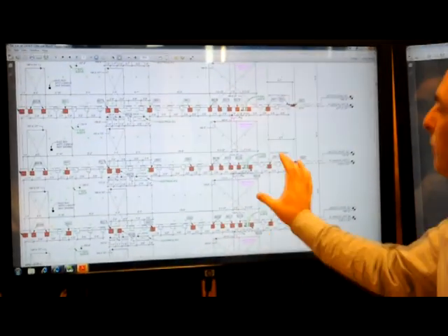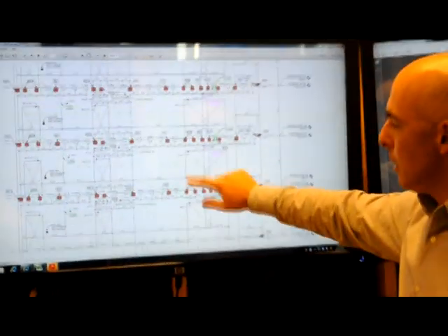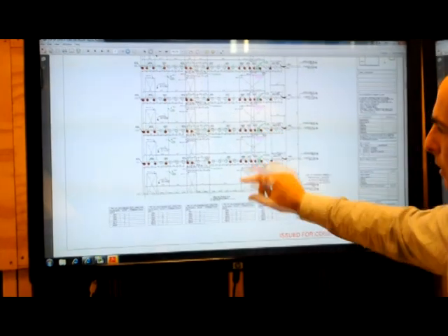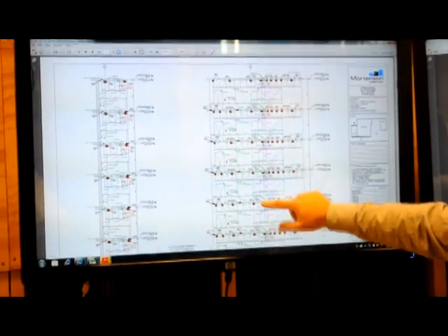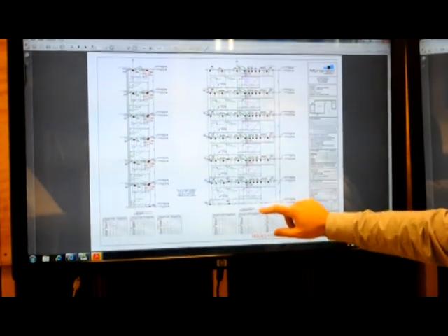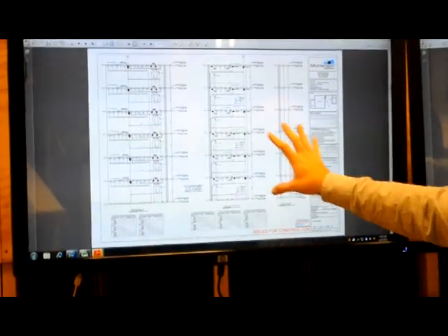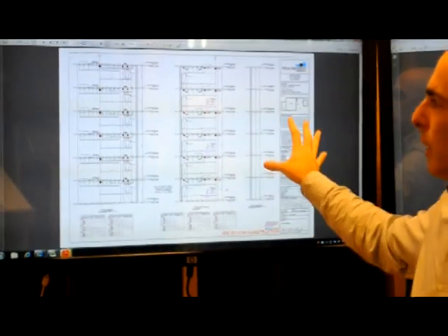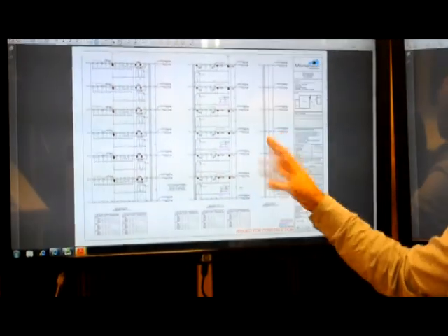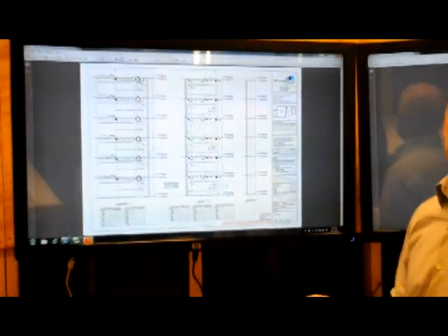So it takes all the design information, all the shop drawings, all the MEP coordination, and puts it in one set of drawings. So it includes all the embeds and schedules here. This is the only thing that our foreman takes to actually build the project. So he can just take a printout of just this, and he can print it out directly from here, or he can take it in the field to our pod and print it from there